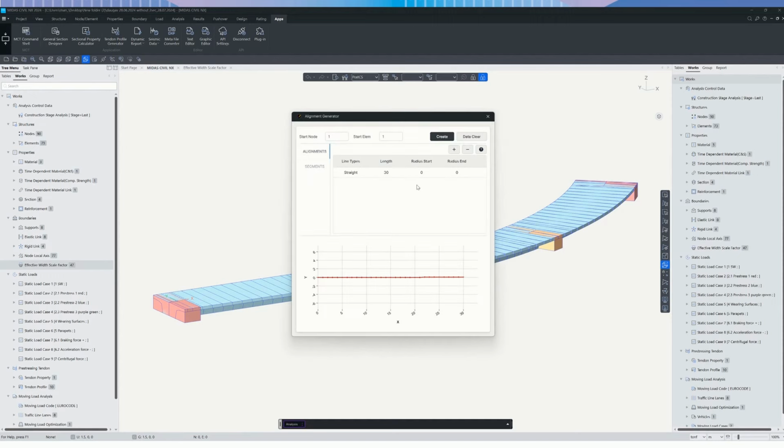There are 2 tabs. On the tab Alignments, enter the parameters of the axis. It should be longer than your design or equal. In the current model, the axis consists of 2 line types. It was straight and arc, so I needed 2.